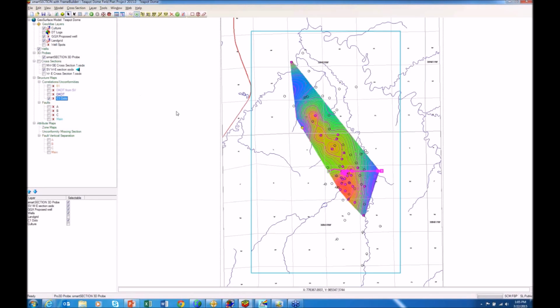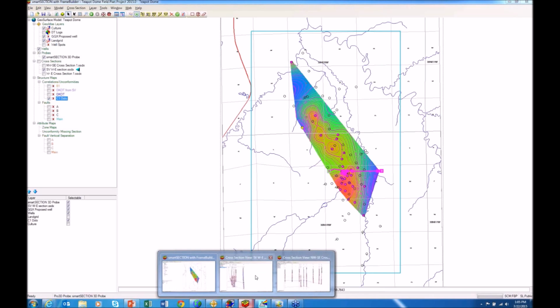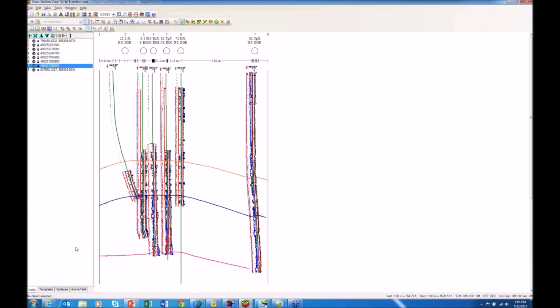What you're looking at now is the C1 dolomite being modeled on the fly using triangulation and minimum curvature smoothing. I've got an east-west cross-section across the feature. Let's take a look at that. You can see that the shallower surfaces are being modeled more consistently because I've got more wells penetrating them. The deeper the structure goes, the fewer penetrations and the fewer samples, so the lower surface is being a little more naively modeled.